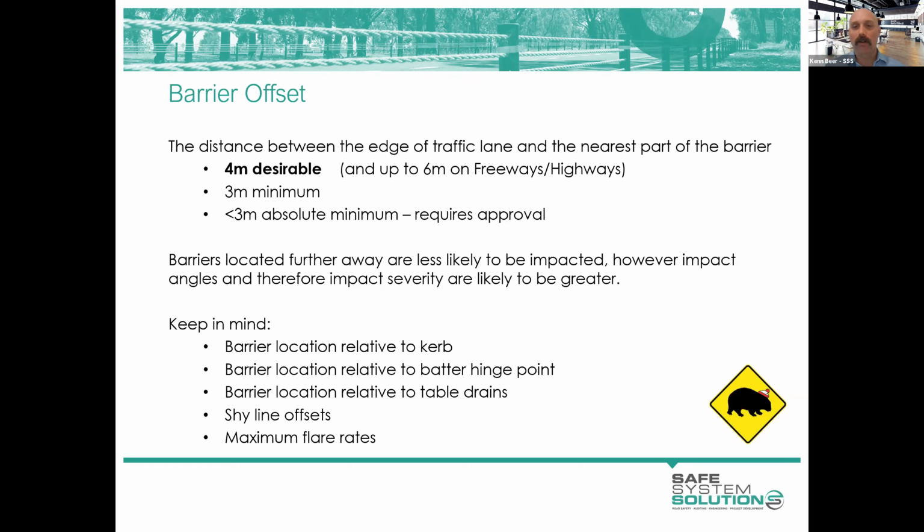He also mentioned that there are a couple of methods for calculating the length of need, the angle of departure or the run out method, and the angle of departure is the one that New South Wales uses. But just be conscious of that if you're getting designers or you're doing the design yourself, that you're using that New South Wales method.